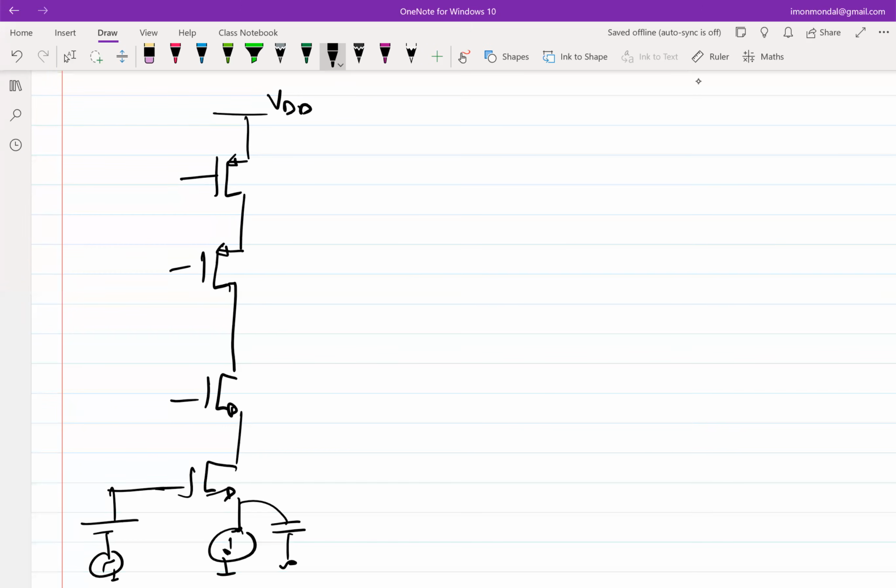So let's say this is M1. Let me now rename this transistor. Let's say this is M2, M3, M4. So M3 is the cascode transistor that is shielding the M1 transistor, increasing the output impedance looking down. M4 is the cascode transistor on the PMOS side that is increasing the output resistance looking up, right? Looking into the drain of M4.